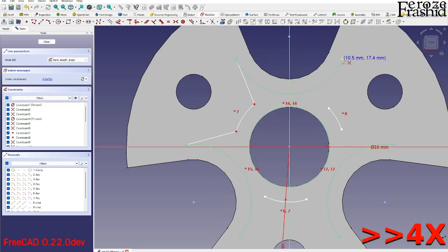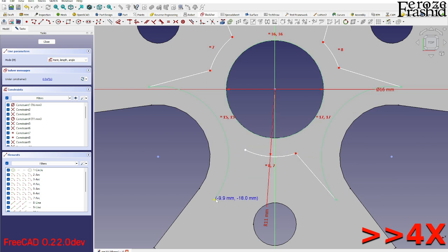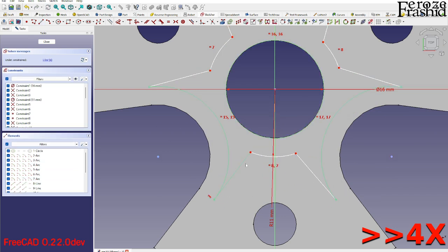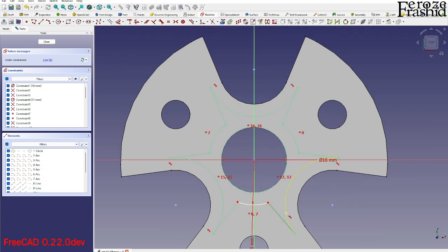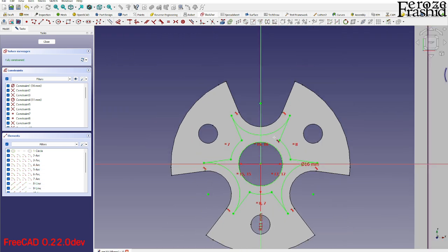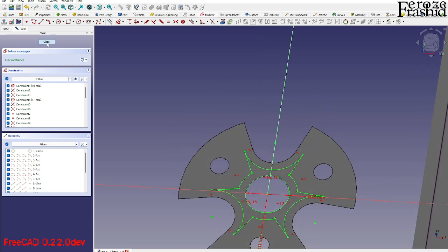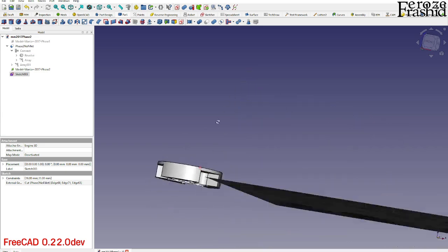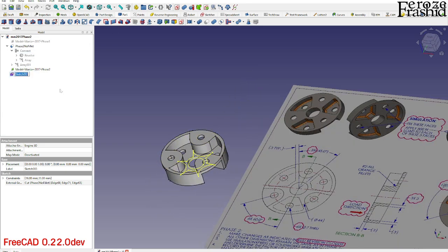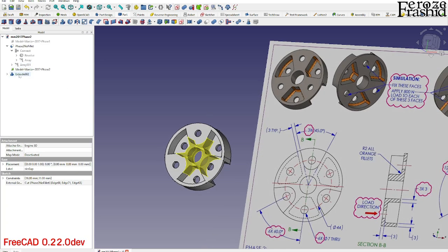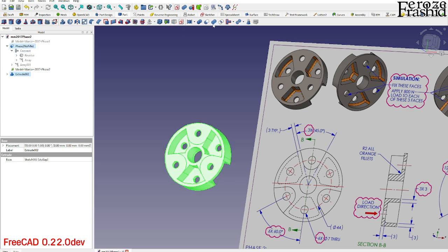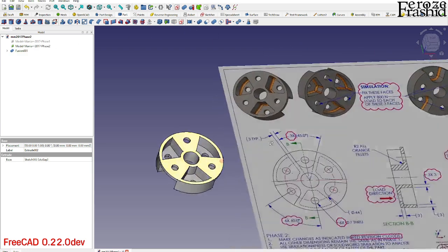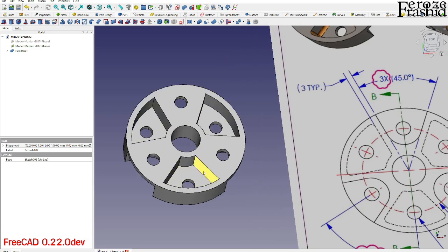Okay, now take the line and connect these two. So do that 6 more times. All right, so this is the gap that we are filling up. I'm gonna go ahead and close it out. So that's the sketch, and I want to rename that as a sketch gap. Right, extrude that up by 15 millimeter, and that fills up everything. Now I can go ahead and make these two one fusion, and that is our phase 2. Well, of course without the fillet, but that's our phase 2.